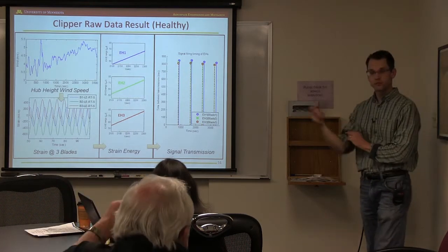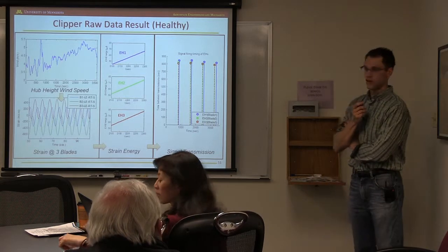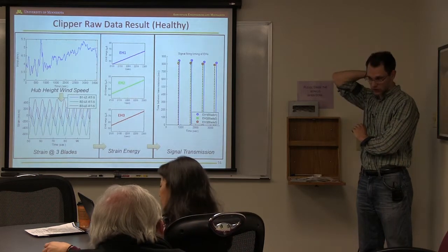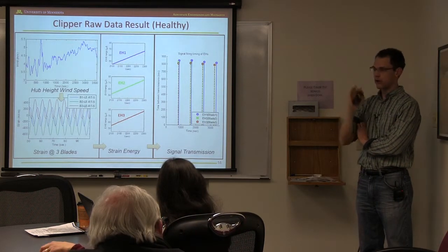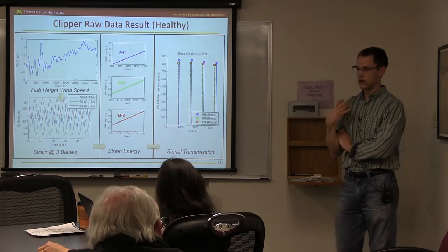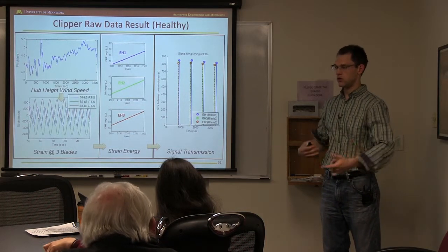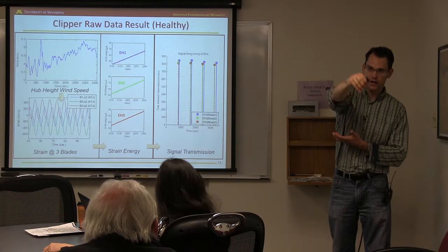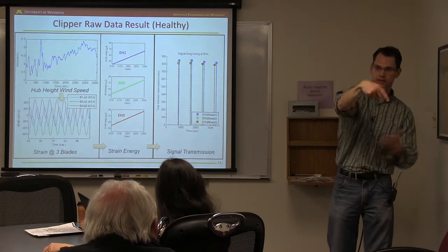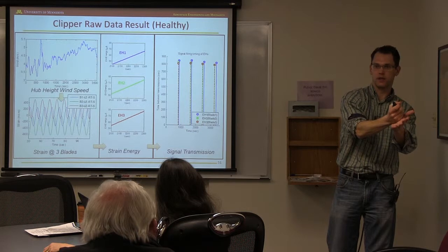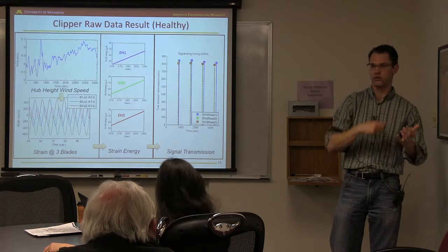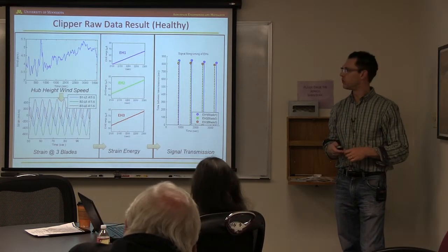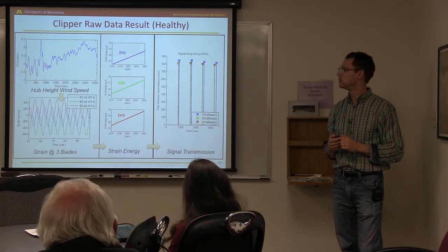Okay. So on the Clipper, you do have wires going to the strain gauges. We do. And to wire this, though, I don't have slides of this, it was quite a challenge. We had to do this after the fact. So they had already built the blades, and so we had to install this after the fact. So we had the blades on the ground. One of the graduate students had to build a little robot that crawled deep into the blade. And then when it got to the location you wanted, it had a hydraulic actuator that then slammed the sensor to the inside of the blade, and it had some epoxy. And so he built sort of a one-off robotic arm that could crawl to different parts of the blade. So conceivably you could do that for the install.